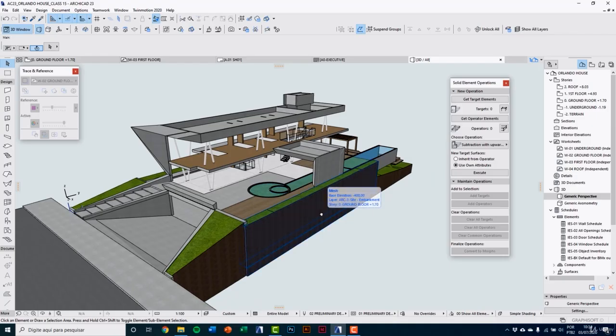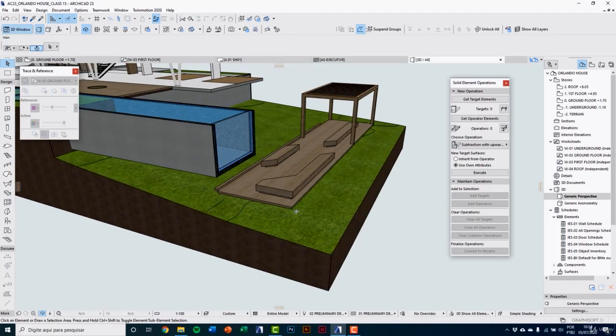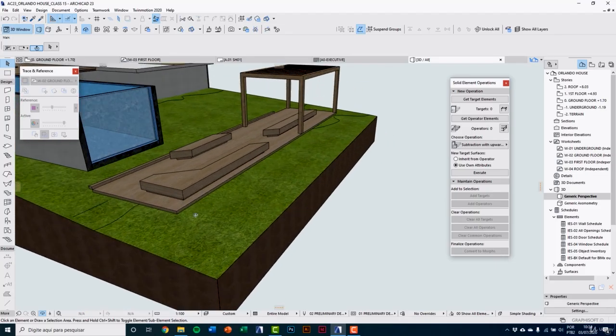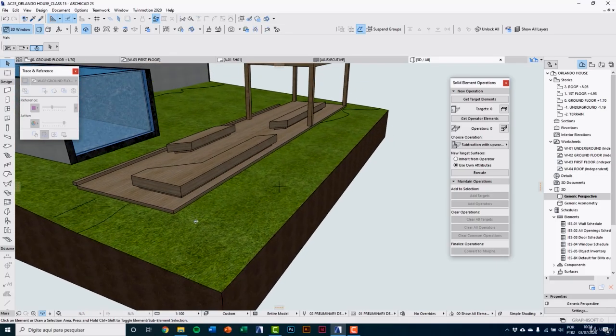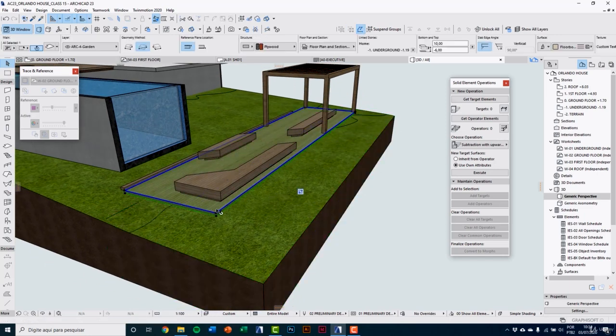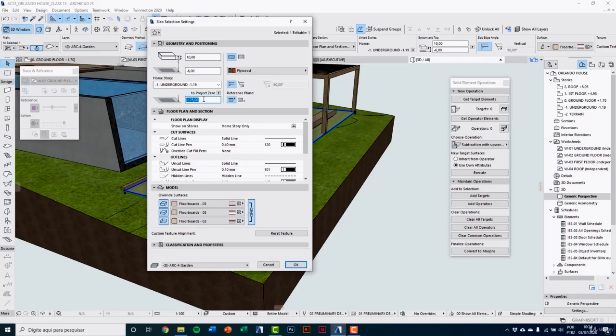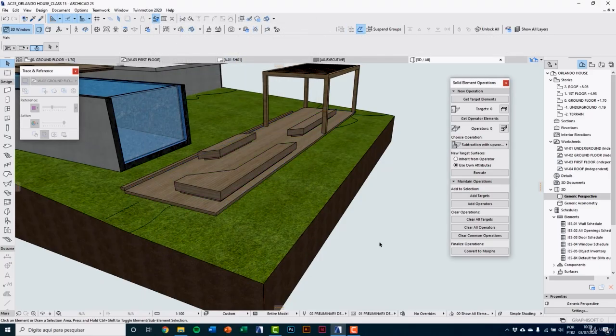Now I'm going to do the back part, this part near this wood deck. Here I will have a plain grass area, select the deck and check the level, which is minus 125. So I will elevate mesh points to 130, 5 centimeters below. Go into terrain.